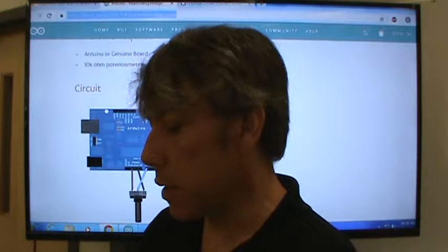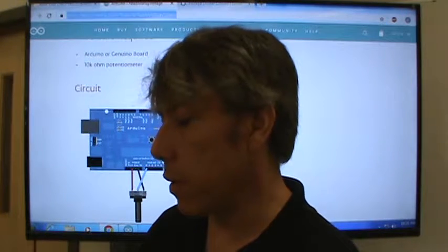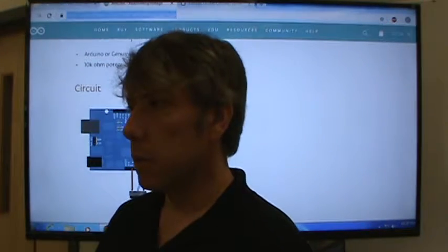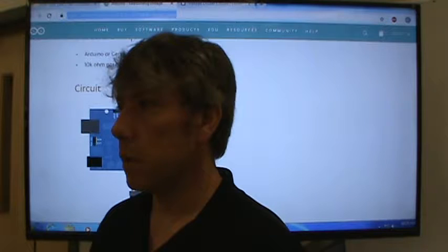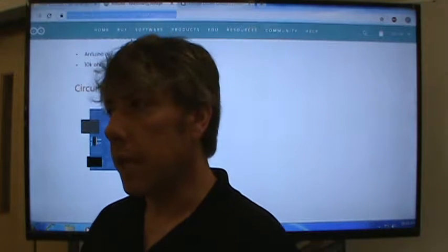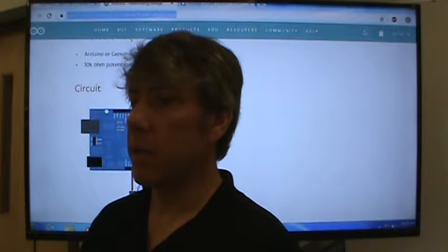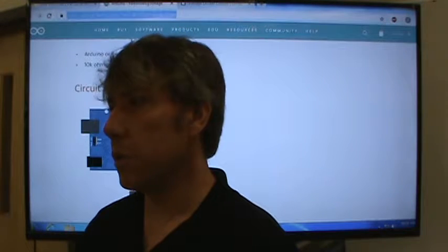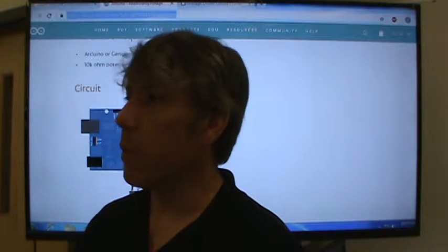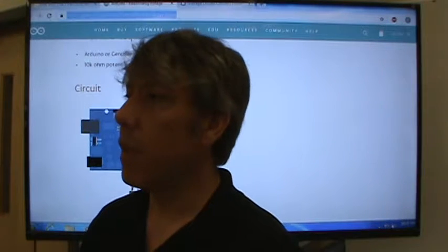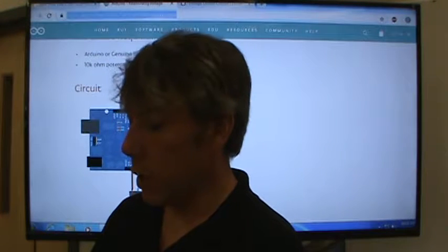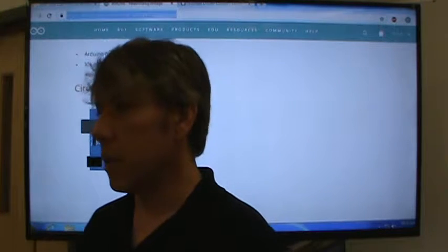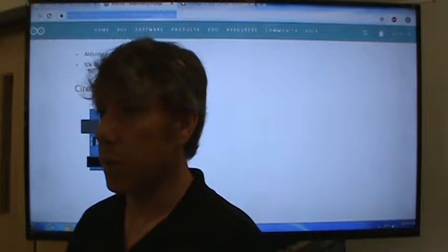If you look on the side of this, it says R103. Any guesses what that might mean? R is for resistance. 103 ohm. You'd think, but remember the way that resistors are coded with the color coding? Usually your first 2 colors are a number, but then the next one is the number of zeros. That's the way this works. So 1 0, and then the 3 means 3 more zeros. So this is in fact a 10K potentiometer, which is very common.